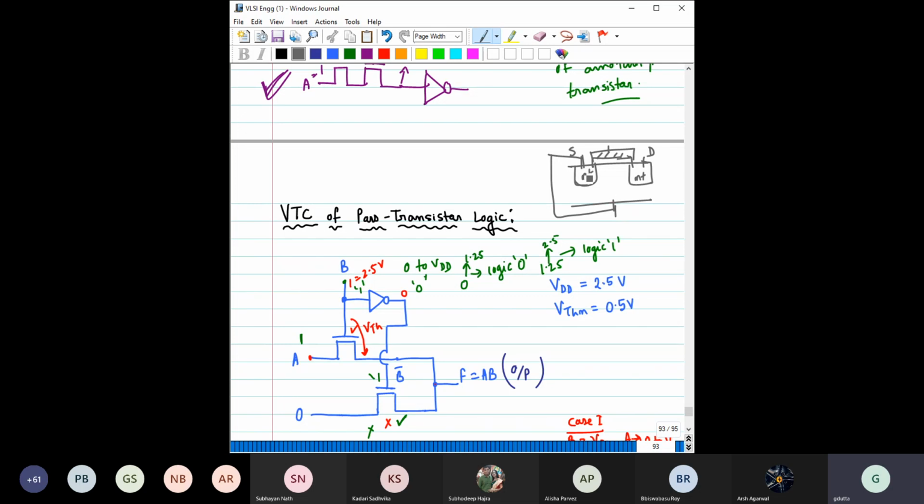These two are shorted, right? Source and this body terminal are shorted, right? Now, as you are changing this voltage, means as this V is changing, are you not changing this bias? Source bias? Yes. If you are changing source bias, you are changing the bias across this, right? Somewhere that is fixed. So are you not affecting the total threshold voltage of this transistor?